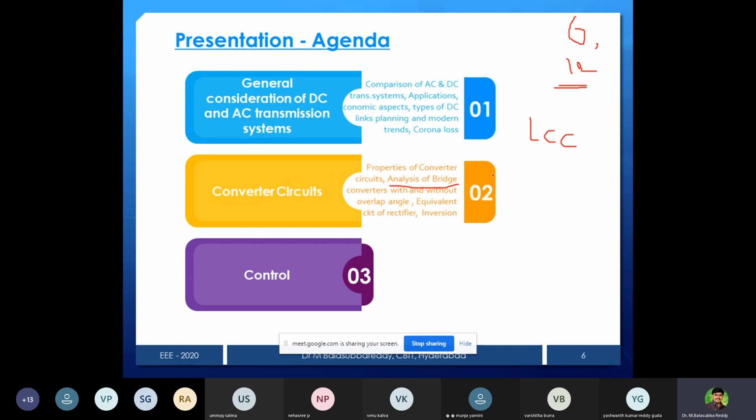Because we are transmitting very high voltages across the valve, as we observe in power electronics also, there is voltage across the device, VT, VT1, VT2 and so on. We notice that when the device is turned off, a reverse voltage is applied across it. It must be capable of withstanding that voltage, because at very high voltages, if the valve fails, there is automatically a lot of fluctuation in the voltage level. That's the reason we are using a line commutated converter. The device has to be turned off very smoothly, and that is the reason we preferably use a line commutated inverter.